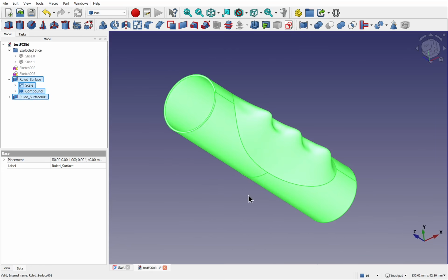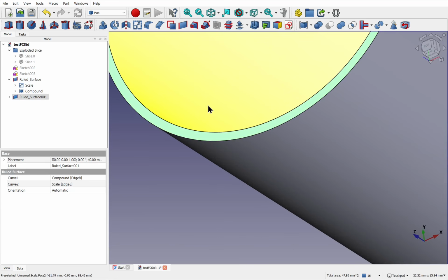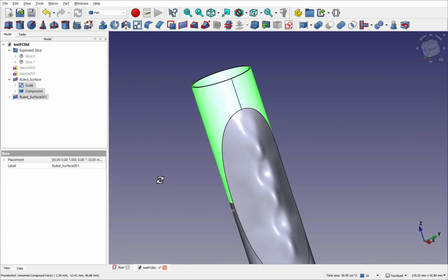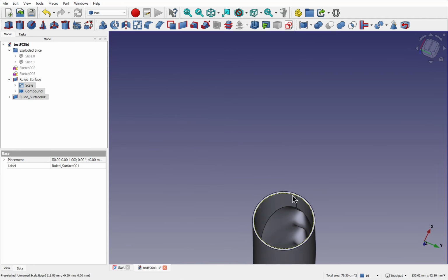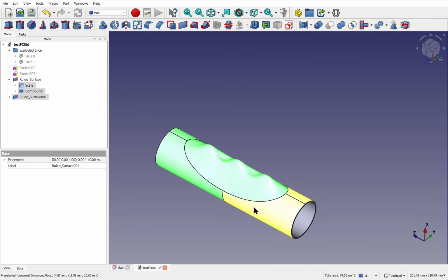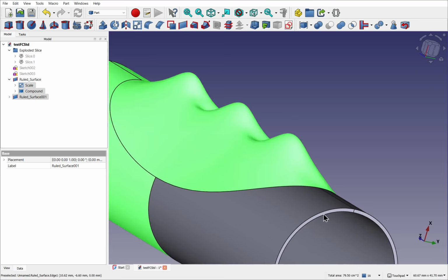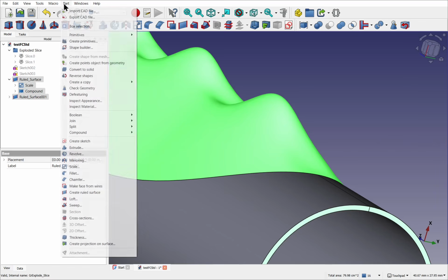So everything's selected. Could select them from screen, and if we do that, you can see inside, outside, you can see them selected on the left hand side here, and this one here, which is actually the outside. So this is where it's getting confusing because you're actually selecting faces. So it doesn't look like the whole of the object is selected. Let's come in and control select that. See them all selected on the left hand side there. Part, compound, and make compound.